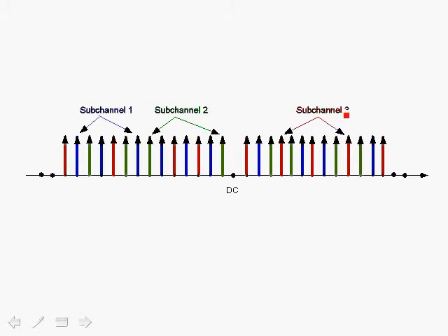And also for subchannel number 3, which is in red. So this diagram illustrates the permutation of the carriers so that although we will show a subchannel as being a continuous color, for example, red or green, allocated to a data burst for a user, in reality the carriers are not adjacent to each other but are permuted and actually are scattered about in such a way as to provide immunity to multipath fading channels.